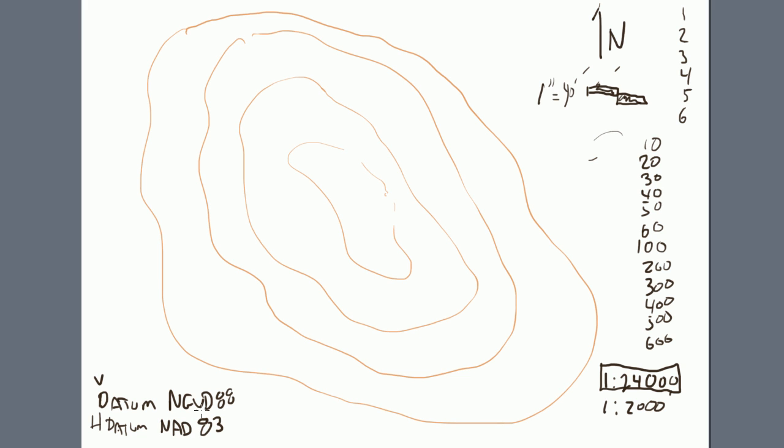And finally, you very often have the coordinate system, which ties into one of these two things as well, and we use the state plane. Now, many of these things, they're implied. But let's not make them implied. This is not implied. You must do it.